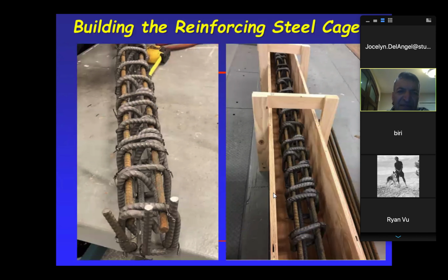This beam doesn't have these in it. One group doesn't just have 4 bars, and we just put one stirrup at the beginning, one at the end, just to hold it. But we didn't put any of this in. Why? Because we wanted the beam to fail in shear.